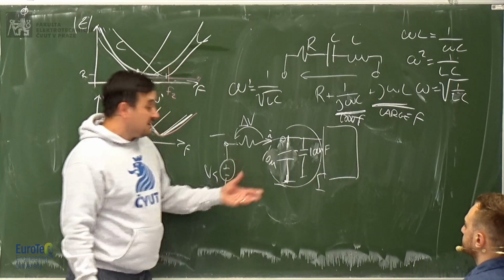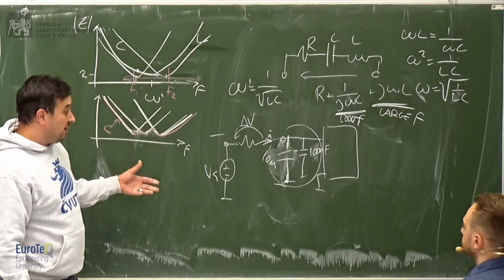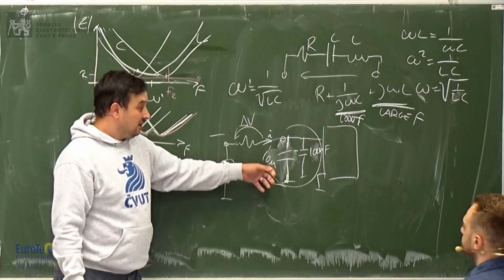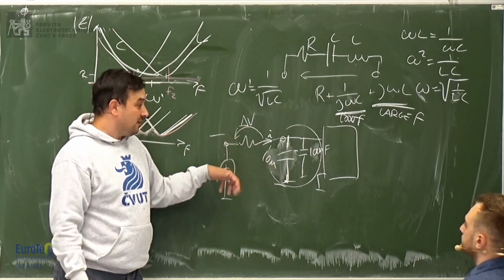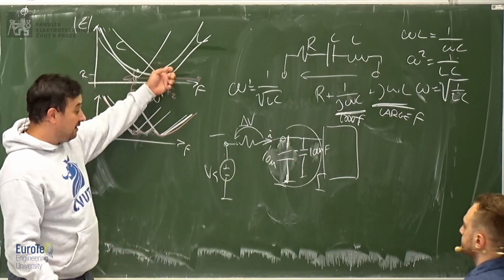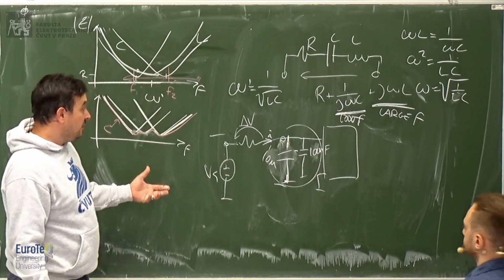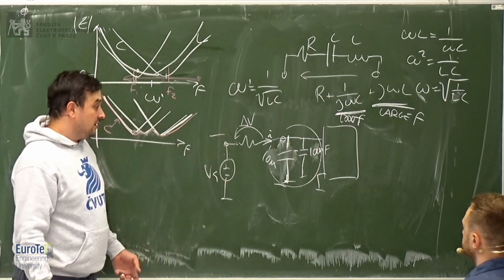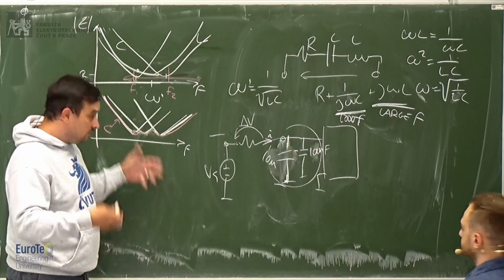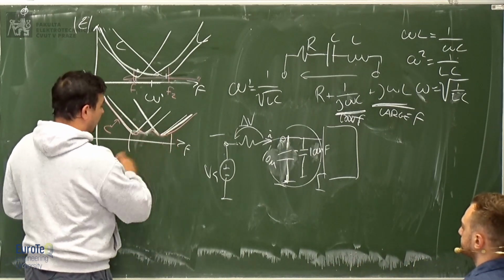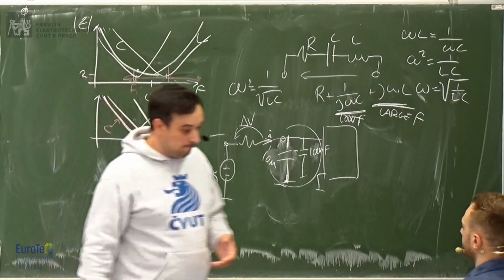But if you consider that there is also an inductive component, then this capacitor is not ideal, suppressing everything over some frequency, but it has this inductive component which screws everything up. So if you want to suppress also that frequency, you need another capacitor to make it more selective. Then you make your calculation. Okay? Very nice explanation.